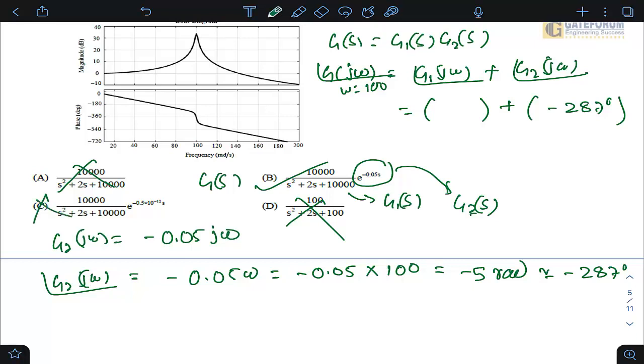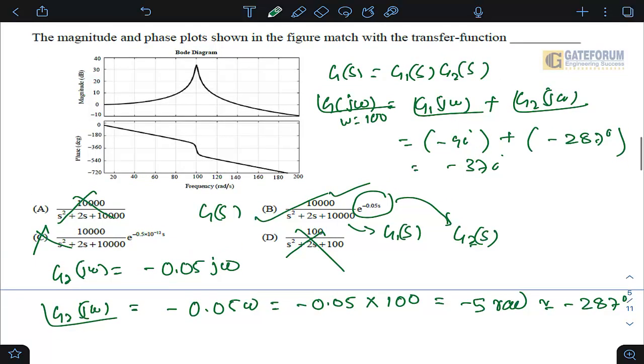If you want to satisfy yourself in a more calculation way, then you simply find the phase of the transfer function at frequency 100, and you check it out. You will definitely get it is almost close to minus 90 degrees, and if you check it, it will be coming in the range of minus 37, which is perfectly satisfying this criteria. So the answer has to be option B for this. It's a good logical question, students, right? I like this question because using your skill, by observing the options, you have to tell the answer rather than going into too many calculations.